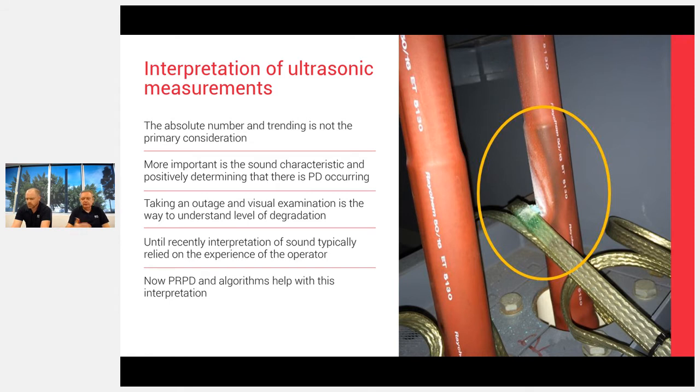So in this particular instance, we've taken an outage and we can see we've got a problem here. We're going to have to replace that cable termination just because of the sloppy nature of leaving large earth leads in the wrong place here.